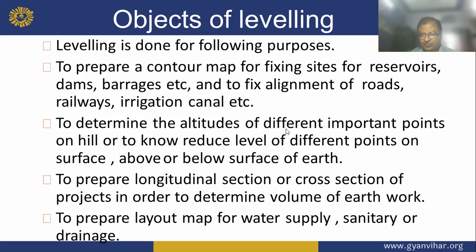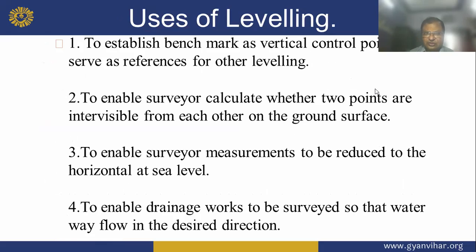Determine the altitude of different important points on a hill, or to know the reduced level of different points on the surface above or below the surface of earth. To prepare the longitudinal section or cross section of a project in order to determine volume of earth work, and to prepare layout map of the water supply and sanitary or drainage. So use of leveling, you will read.